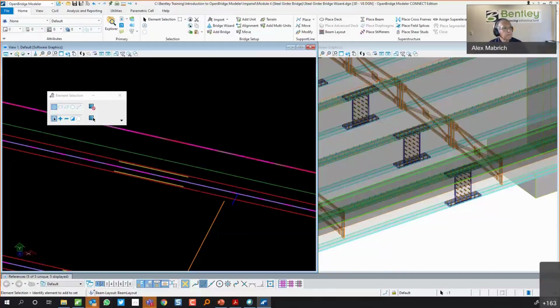Now, existing substructure and existing beams need to be checked for the new deck. You're right. Yeah, you need to model them and check them. So not only that, the existing substructures, depending on the rules of the state or the DOT, sometimes if you touch a bridge, you've got to retrofit the entire thing. So you need to make it up to code, not just the widening part, but the entire bridge. So this could be quite challenging.